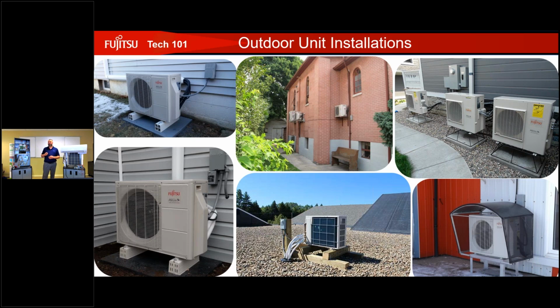And then one more thing that I like to point out here, when we look at the top middle, nice height, good to go there. The only issue is there's a bench right underneath it, and these units tend to condensate. So you might want to think about it. If it's a movable bench, fine. If it's an immovable bench, maybe a different location.